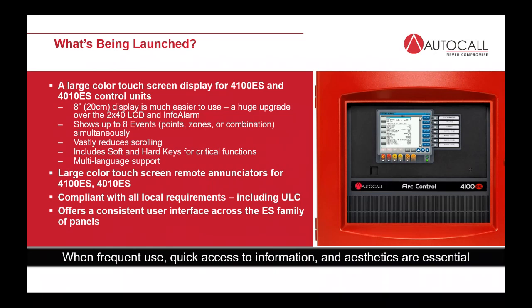When you look at that display on the bottom, you can see the colored icons that we have, the standard icons for fire, priority 2, supervisory, trouble, acknowledge, and reset. And on the 4070S, those are not functional switches or functions. You have to actually touch the button above it on the touchscreen display to be able to perform those functions.